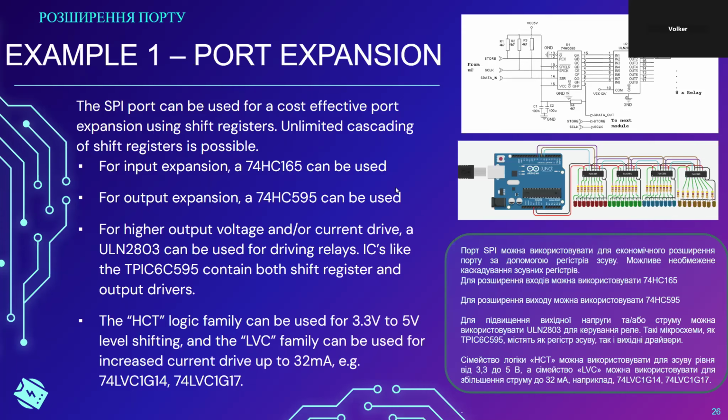Is it an AC motor? Is it meant for 220 volts or higher? Or is it a DC motor for 12 volts or 24 volts? So let's say it's DC motors. It's a DC motor. Okay. If you were using a DC motor, I would probably either use a MOSFET or an integrated driver.